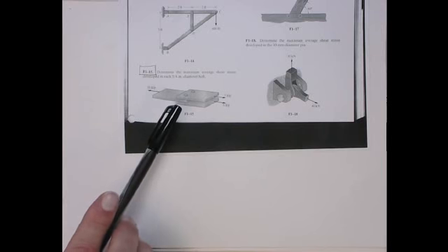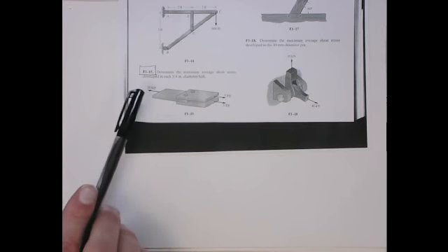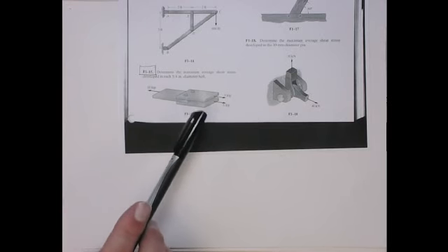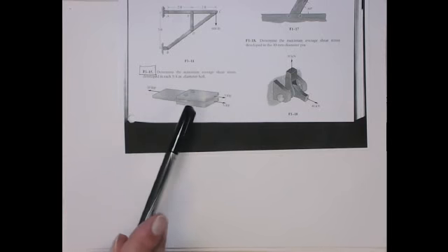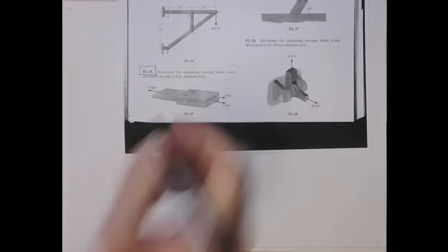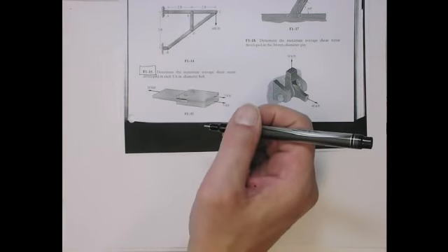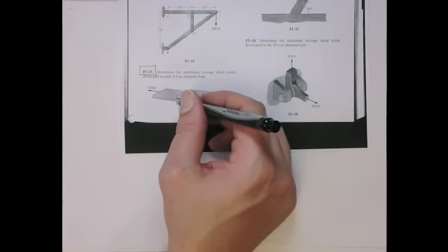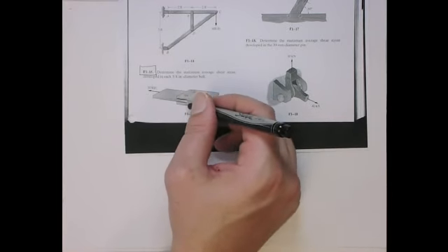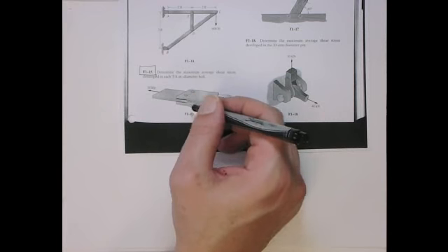So here are 3 plates, and they're held together by 2 bolts going through. The loads on the plates are shown here. This is actually what's called a double shear problem, because you have 2 shear surface areas. One between this top plate and the middle plate, and another shear line between the bottom plate and the middle plate. So these bolts act in double shear because there are 2 lines of shear going through them.